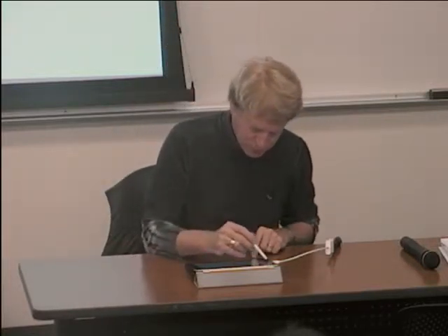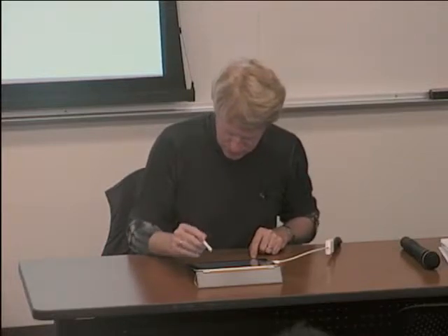Now, that's the whole idea. It's very similar to an associative memory, but it's going to take a lot more arithmetic. Because if you think about it, in an associative memory, what you have to do is just a comparison. Here, I have to do a distance computation, and I have to compute a minimum inside the memory array. Okay, so let's go back to the slides here.